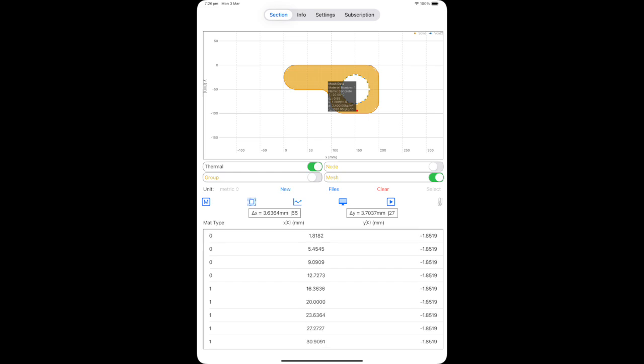Next, the boundary conditions for the model will be specified. Toggle on the Node Toggle button to show the external nodes. Double tap on the node text of the Node Toggle button to show the internal nodes. For this example, no boundary conditions will be applied to the internal nodes. So double tap on the node text of the Node Toggle button again to hide the internal nodes.